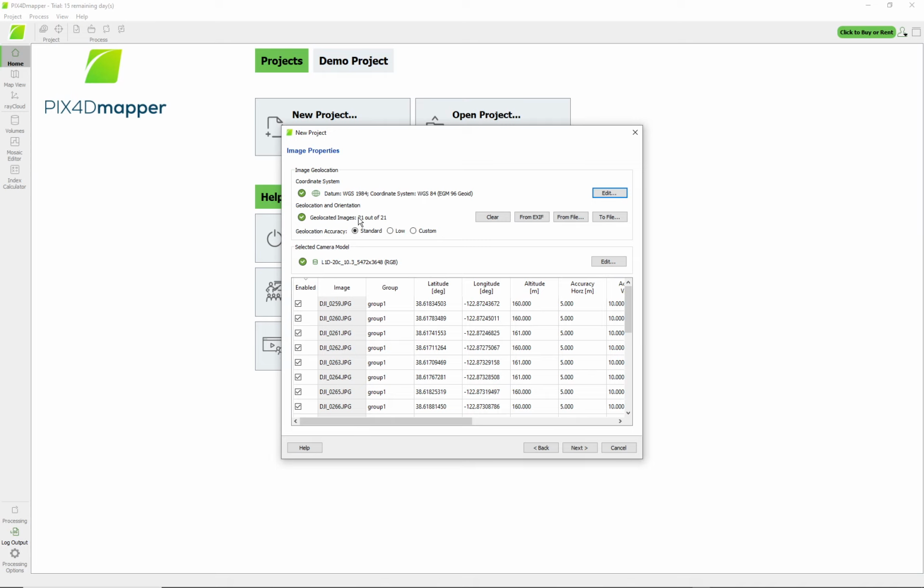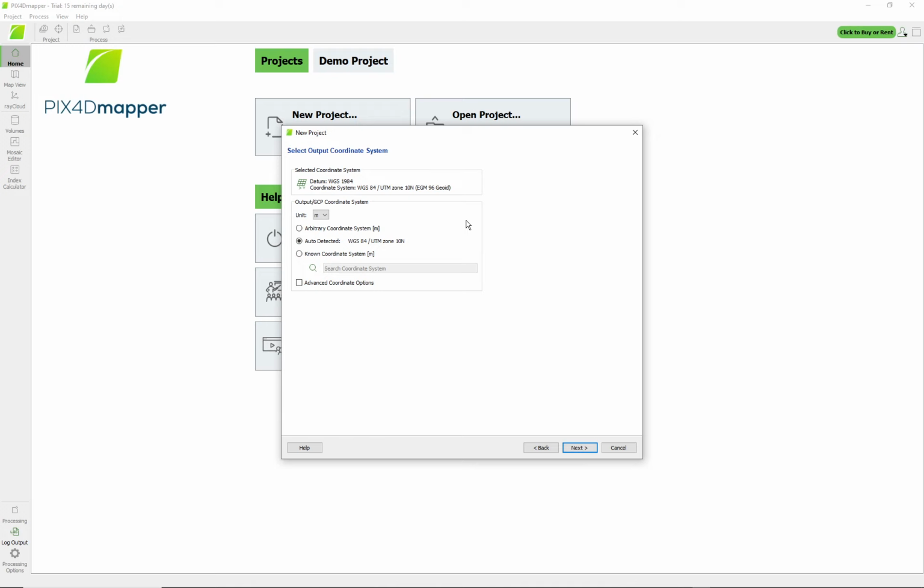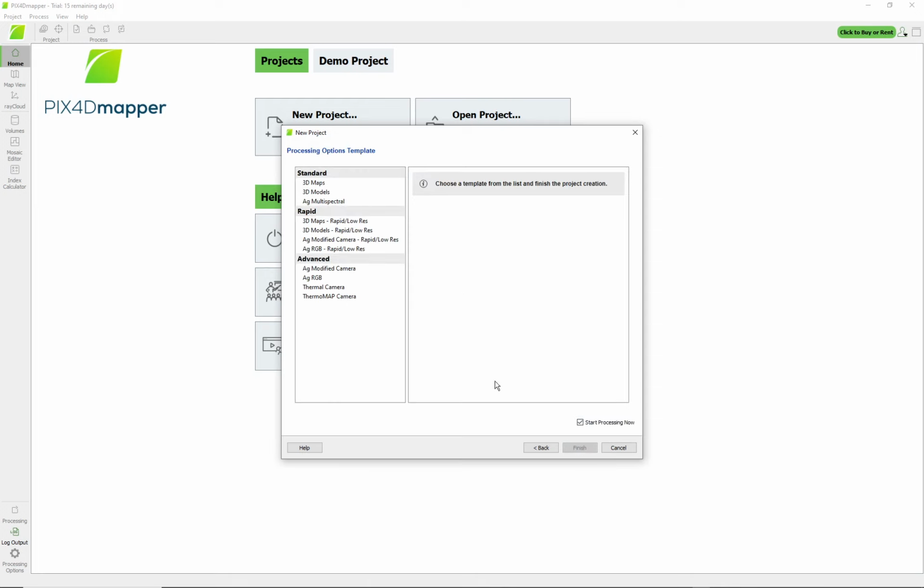When one flies drones, it's really easy to think that you're recording geographic information. I'm going to start this cooking as I'm talking. The drone will say GPS recording, but it turns out that to truly be in GPS mode, both your GPS signal needs to be working properly, you need to be in touch with all the satellites, and your compass needs to be working, which means that you can't be too near metal objects. And that is, I think, one of the most common modes of failure with drone photography. I'm going to forward this while I'm talking. So I'm just going to say next here.